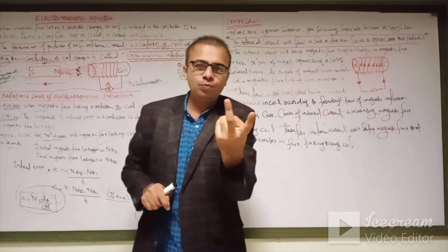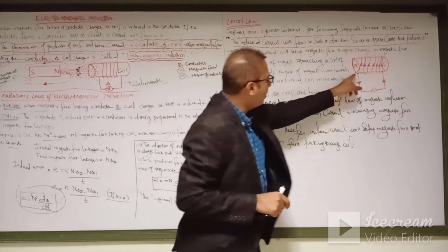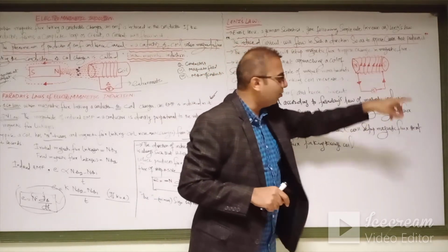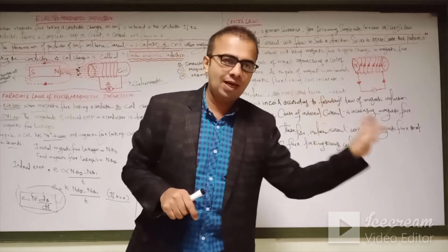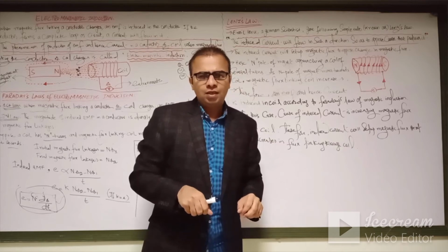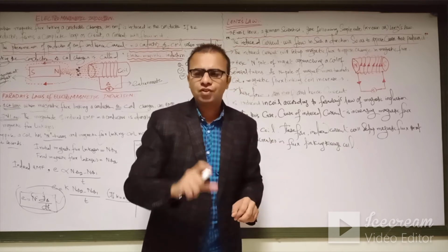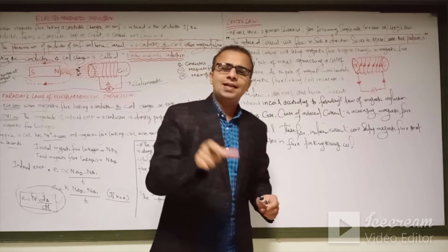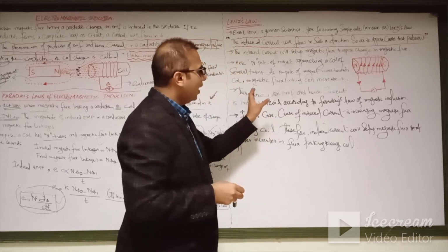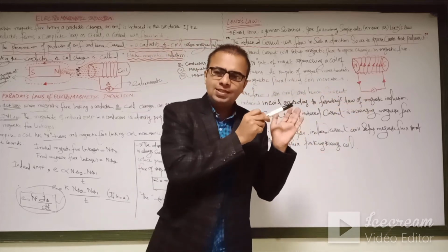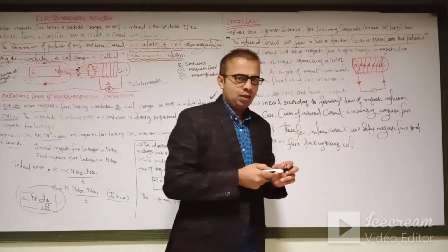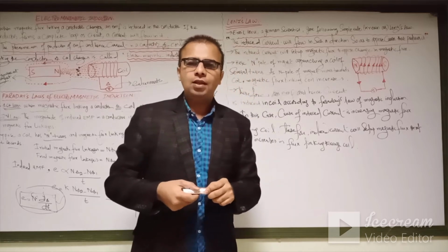Each and every magnet has two poles, north pole and south pole, and the coil has a number of turns of wire wound on the magnetic material, and the galvanometer is used for measurement of the induced current in the coil. Now if we take the example of the DC motor, the DC motor has two windings, the armature winding and the field winding. The field winding is excited from the DC supply to produce the magnetism effect, and external DC electrical energy is supplied to the armature winding. Then what happens?